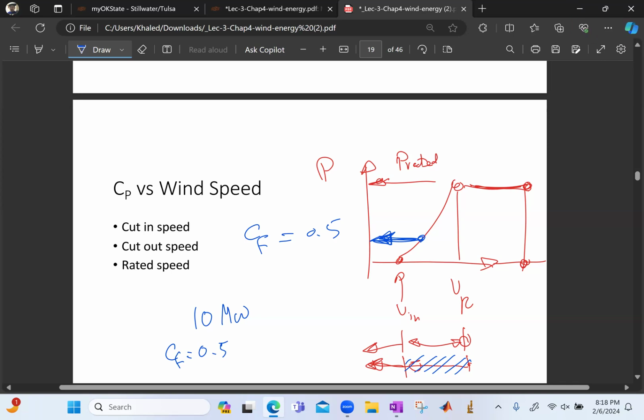You're not compatible, right? The wind turbine is amazing, the site is pretty good, but it's not for that kind of wind speed. There is always wind, but always at 7 meters per second, and that turbine kicks in at 7 meters per second. Zero power out. So the CF isn't a characteristic of the site itself, it's a characteristic of the wind also. It's the multiplication of both of them.